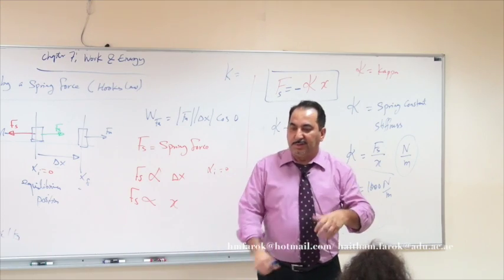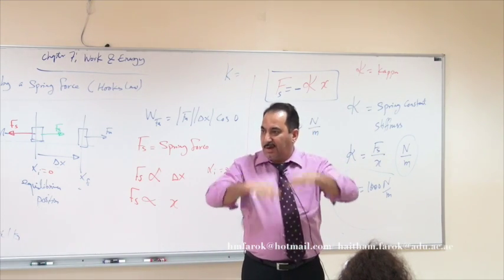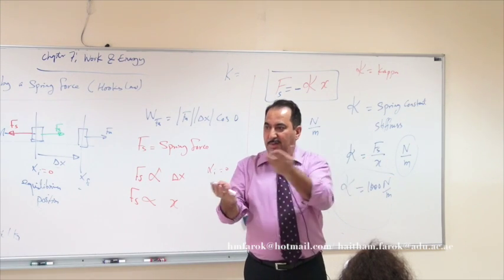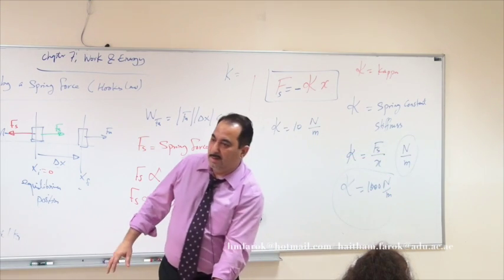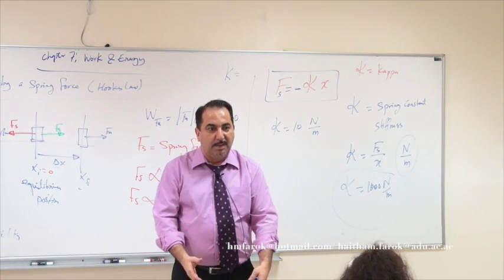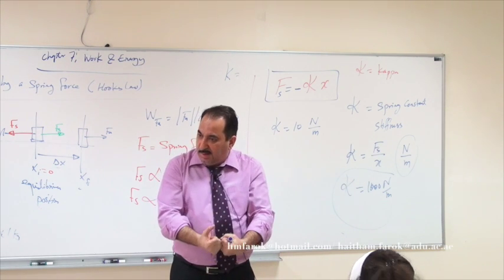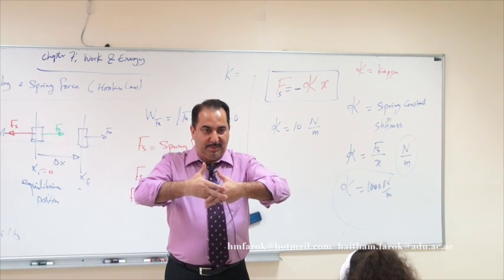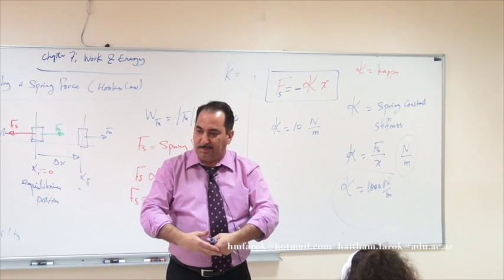So instead of the building taking the shock and starting to vibrate, going up and down or moving sideways in a shear wave, what happens? The energy goes to the rubber or the spring. The spring will be compressed, so it takes the energy, and then it releases this energy not in one go. Probably 1, 2, 3, and stops, yes?